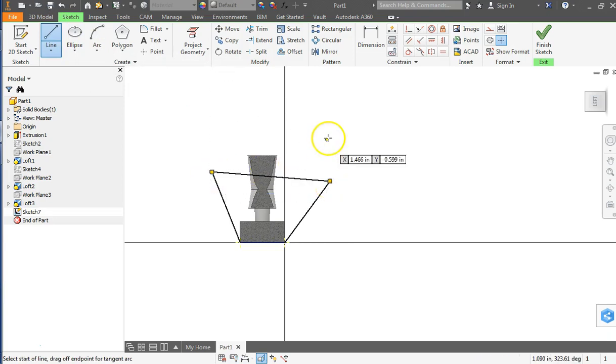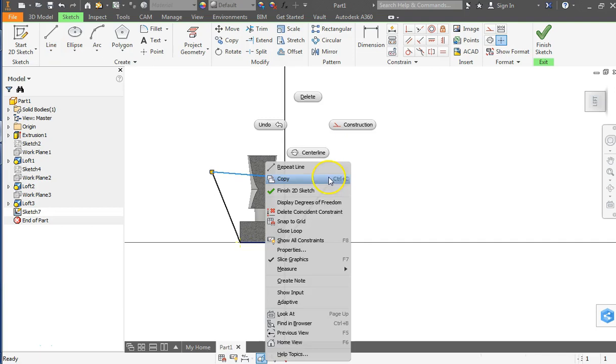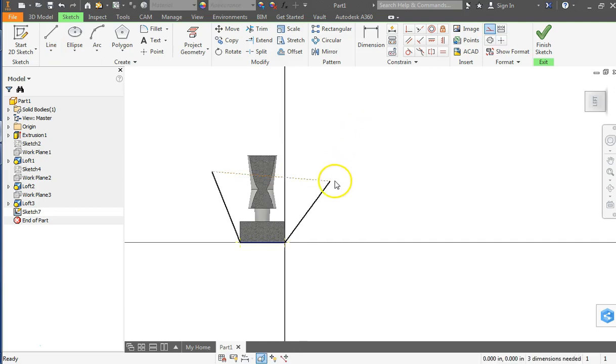And I'm going to make this line, I'll call it a construction line because it's really just to help me out here. I want these two to always remain at the same height, so I'm going to constrain this to be vertical. I'm sorry, horizontal. I might have to use the vertical tool though because I'm rotated. So let's see, I think I do. There you go, yeah. Had I used, let's hit undo, had I used the horizontal tool, okay, it wouldn't have worked for me. And that's just because horizontal and vertical is not referencing the perspective I'm looking at, but kind of the original front view. So choose that, there you go.